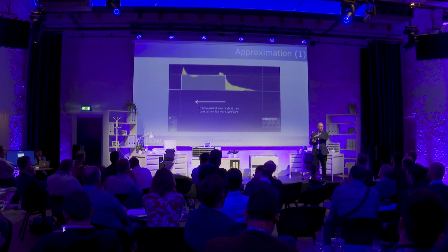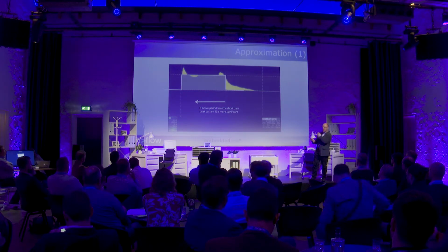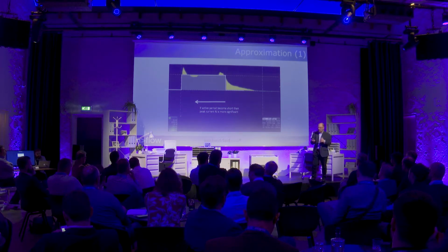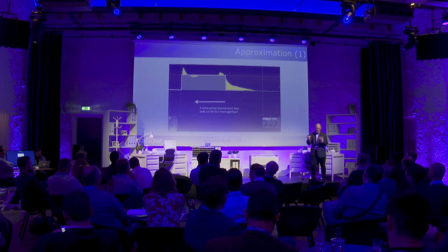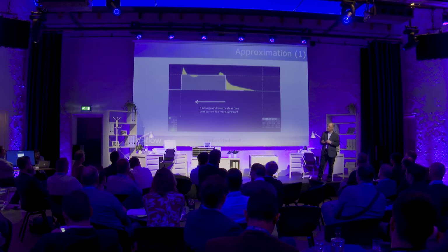So here's the first problem that we see, that we take the microcontroller into a run mode and we think, okay, 10 milliamps in run mode. But actually the area under the curve isn't quite rectangular, so we get this kind of overshoot and then undershoot and then a tail off as the power comes off. Well, okay, that's physics, and that's probably the power supply design making that happen, but just a simple rectangular waveform isn't providing us enough detail to actually quantify the battery size, because we have to allow for all of that additional work that we weren't really expecting the battery to need.